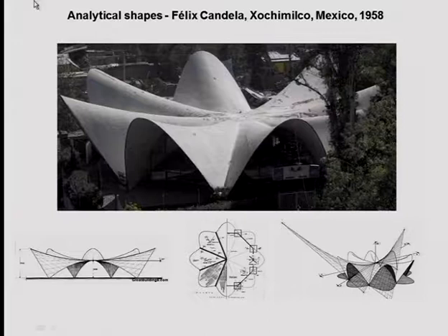You discretize, like in this case, you see here, this hyperbolic paraboloid. You trim it and you get a portion out of it, then a polar array. And this type of saddle is very similar to the minimal surface that you would get with a soap bubble. And if I take a section out of it, the arch I would get is very similar to a catenary. It's not that, but very similar.